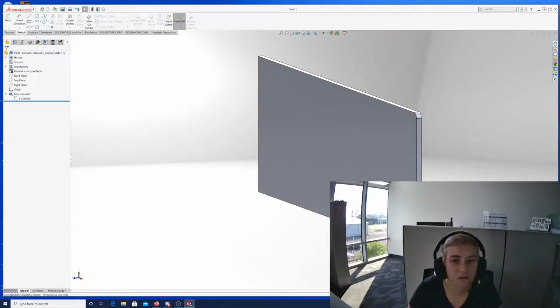if it's fully defined, you can measure the actual mass of the part that you drew, which is kind of cool. Because it's programmed in, 1 cubic meter of aluminum weighs this much or whatever. So that's actually not mass, that's weight. But say you have a meter this way by a meter this way, and then it's half a meter thick, it's going to be able to tell you that's half a cubic meter. And then it'll also tell you how much it weighs depending on the material it's made out of.